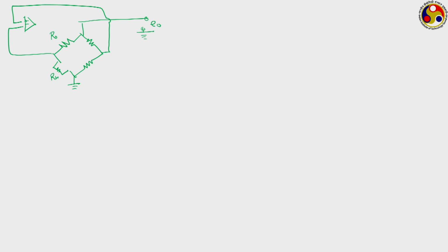This is the voltage that is acting on your source, which has a voltage of E naught. Now, how much is the electrical power being produced? Let us say that is E1. That electrical power will be Ew square by Rw, where Ew is the potential difference acting across the probe resistance. Now, how much is Ew? Ew can be Rw divided by R naught plus Rw, into E naught, whole square, that is equal to Rw E naught square over R naught plus Rw whole square.